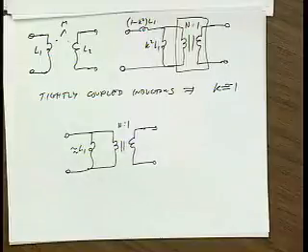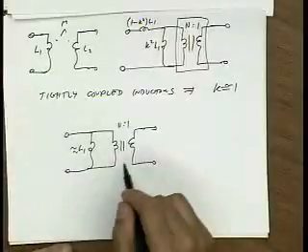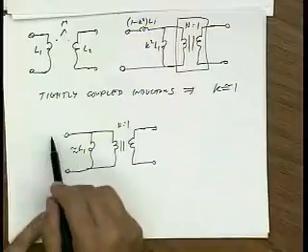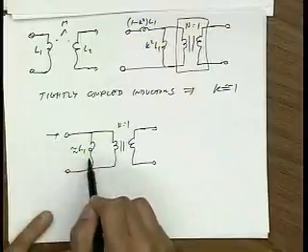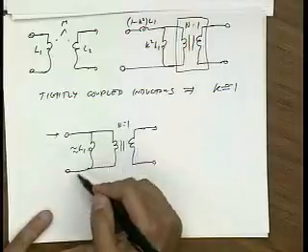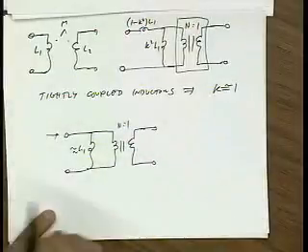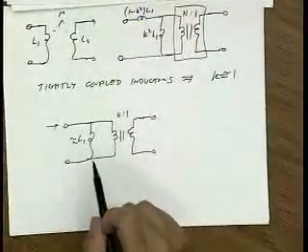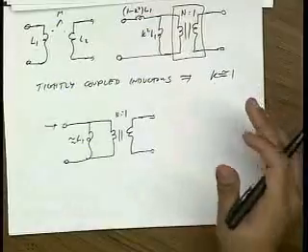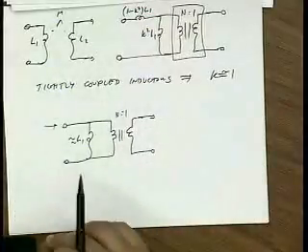And this non-ideal transformer tells us that you can't ever pass DC current through a transformer. If I pass a DC current in here, what happens? It just gets shorted to ground. So any real transformer will only work at AC frequency. Now what's interesting about an ideal transformer is that it'll even work at 0.0000001 hertz. Hey, that's an AC signal, it'll work.